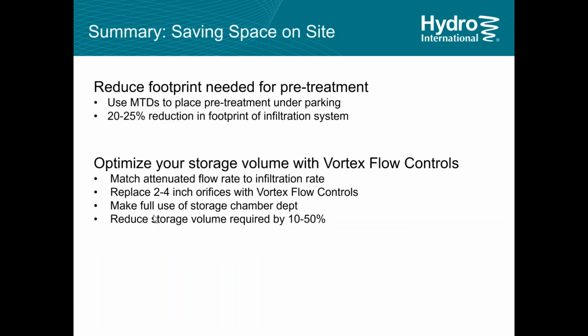So just a summary about saving space on site. Quick way to reduce footprint is put your pre-treatment under a parking space. You can use an MTD to do that, manufactured treatment device. Immediately, you can save 20 to 25% of the footprint of that infiltrating system.